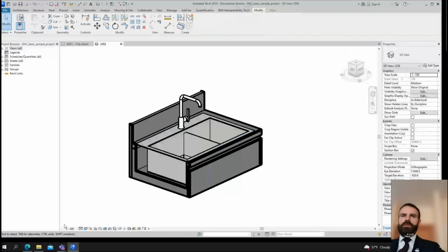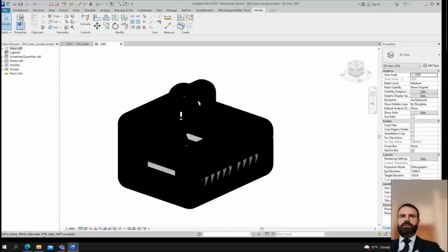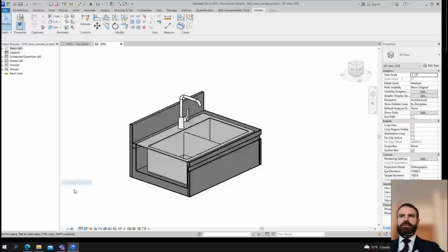Now in the main view, if I look to the 3D view, in the bottom part, I also have this modification tool for each view. So I can choose scale for each view. If I choose too big scale, so lines are too thick, so it means I need to choose the right scale. Next part is detail level.